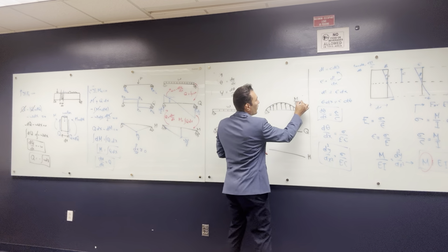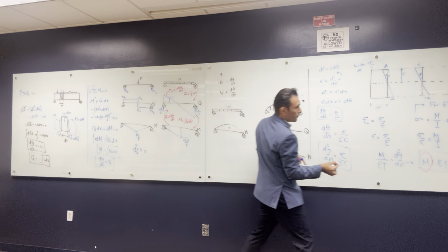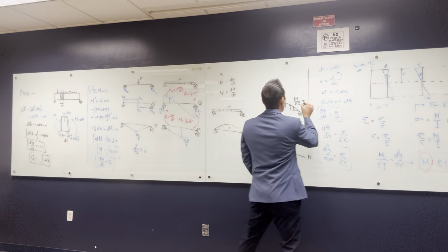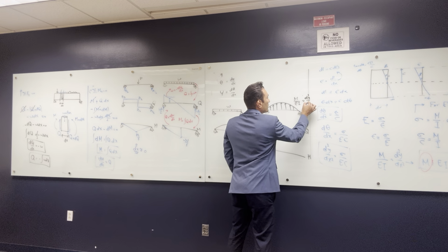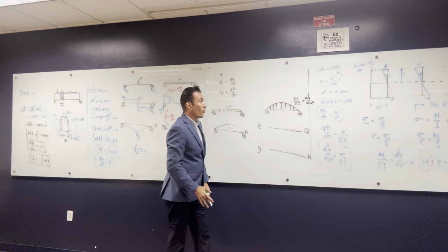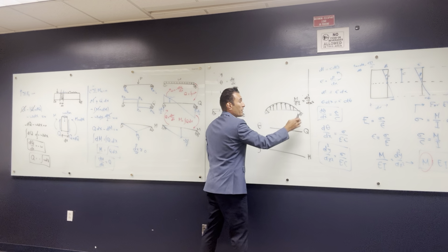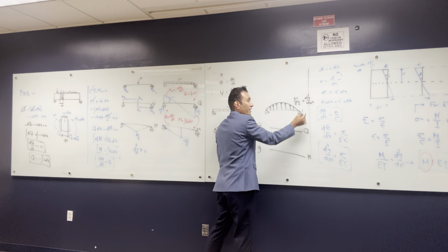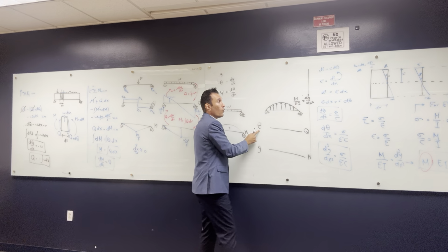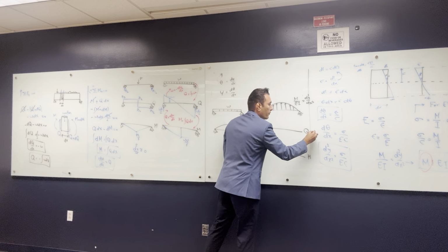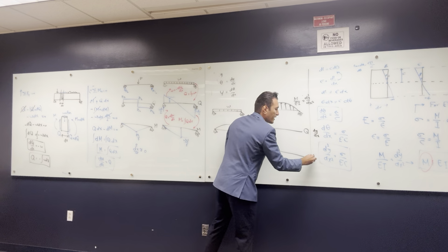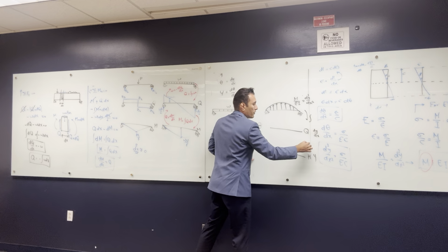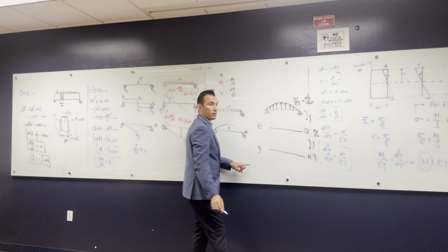Look at this. What is M over EI? The deflection. Here, M over EI is d squared y over dx squared, right? So if I get the shear of this beam, that means that I integrated once. So this has become dy/dx, so that is the slope. And if I integrate it another time, that is gonna be y, right? Here, integration, here, integration, right?